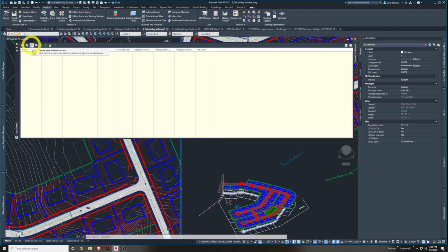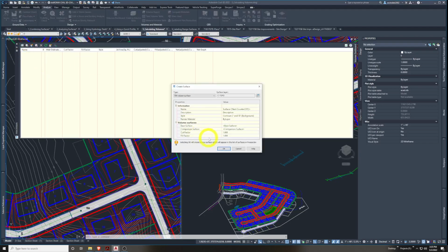So this creates a comparison surface between two surfaces. And we'll accept these default areas. And it's a TIN style. Grid style could go in smaller increments, smaller grid XY shapes. They're generally very similar in quality for accuracy. We'll call this Earthwork. So earthwork of the whole site: what native soils, how much we need to bring in, bring out, can we balance it between what we design and what we have existing.